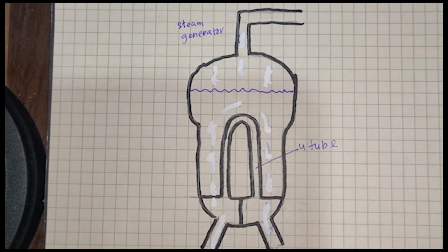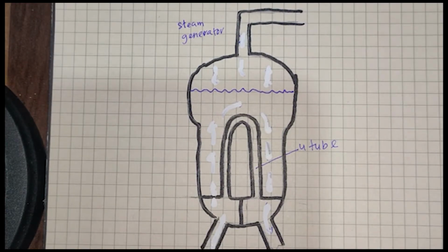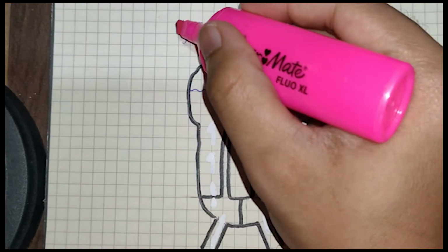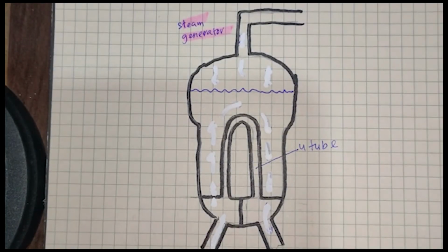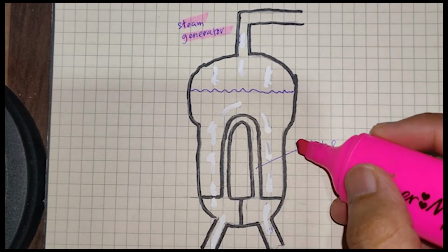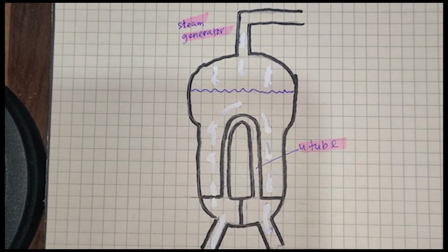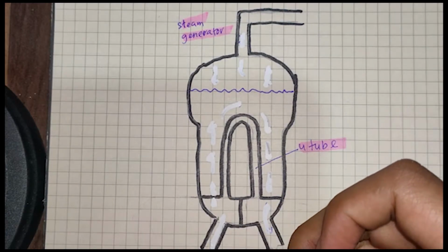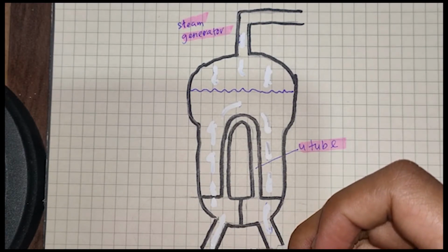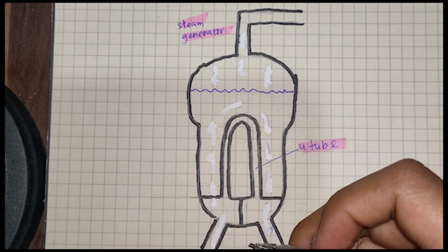After the nuclear fission happens in the reactor pressure vessel, the water is pumped to the heat exchanger. This heat exchanger is also known as the steam generator. In this section, the most important part is the U-tube section. This U-tube is made of various high-performance alloys. The hot water that has been pumped before flows through the U-tube, heating up the metal of the pipe so that any water inside the heat exchanger begins to boil.